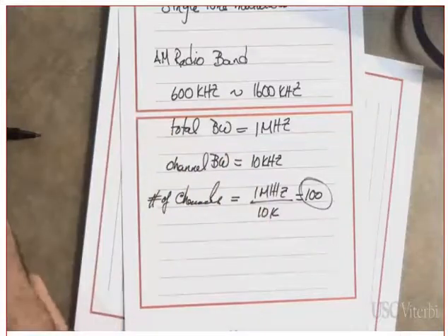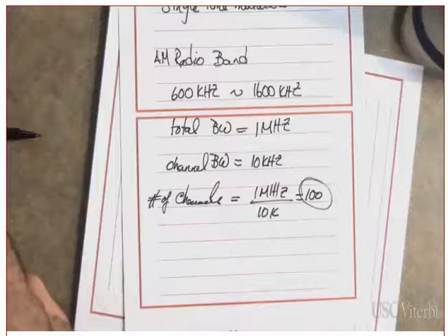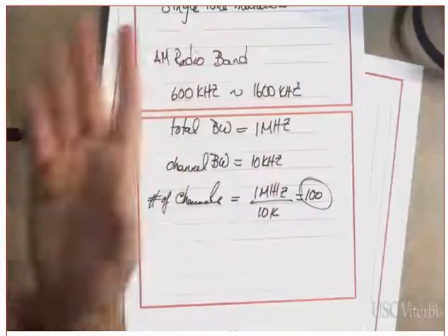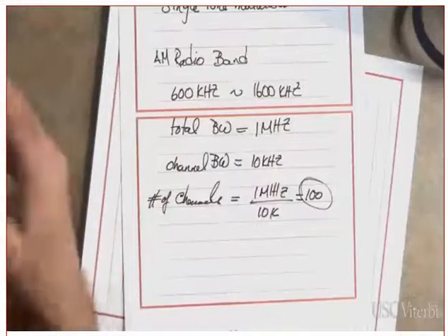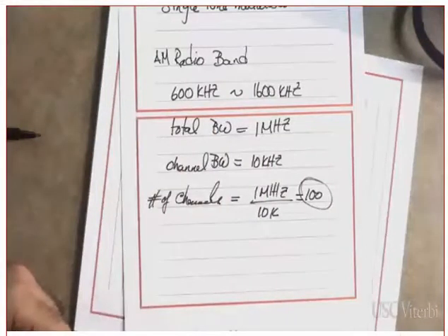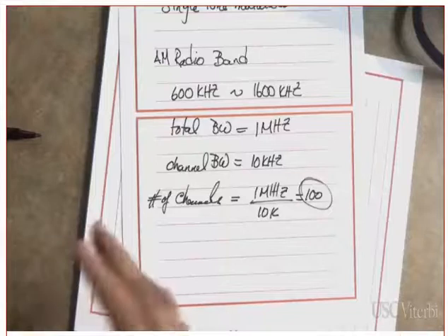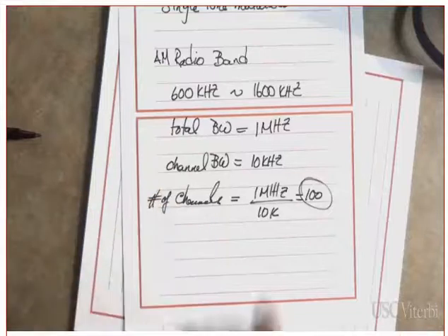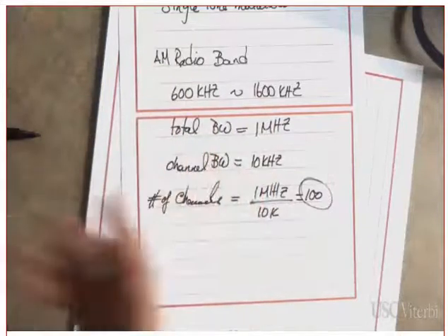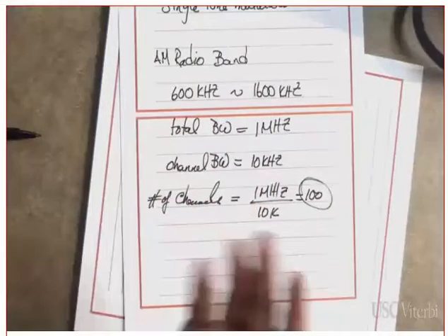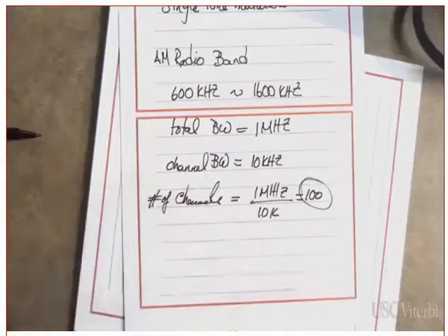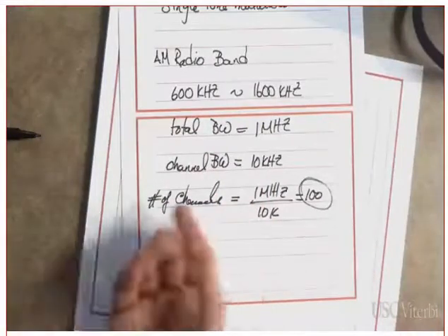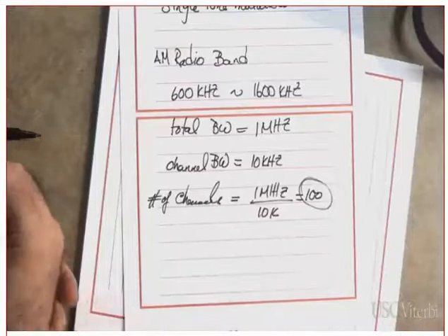You go under a tunnel. You are driving and you go under the tunnel. Do you still receive the AM signal or no? Why? The signal is amplitude modulated, which means the amplitude is going to vary. Because of these obstacles, the tunnels and so on, and the information is on the amplitude, you are going to lose all of it. Whereas with FM, you go underneath a tunnel, you can still receive the FM signal with little degradation. Did you get this or not?